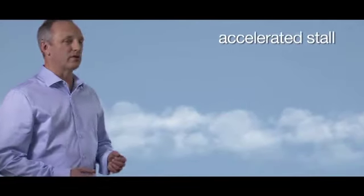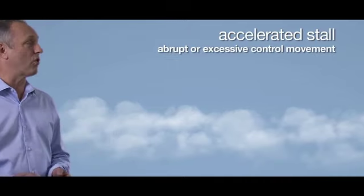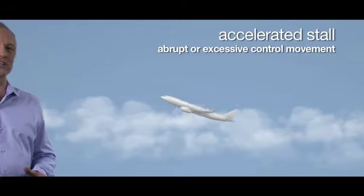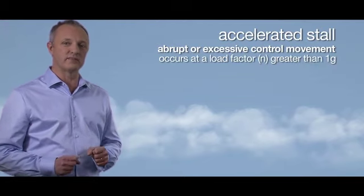That being said, let's now take a look at particular stall phenomena. Accelerated stall. An accelerated stall is caused by abrupt or excessive control movement. An accelerated stall can occur during a sudden change in flight path, during maneuvers such as steep turns or a rapid recovery from a dive. It is called accelerated stall because it occurs at a load factor greater than 1g.